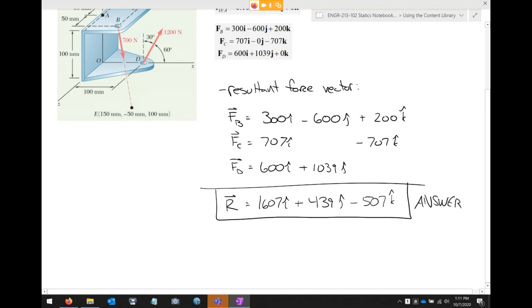And again, it follows the same principle that we've been employing. So that's your force equilibrium. So in other words, I can take those three forces and just replace them with a single force vector that equals this. But that's not enough, because I also have to ensure that I'm meeting not just force equivalent systems where the forces are equivalent, but the moments have to be equivalent as well.